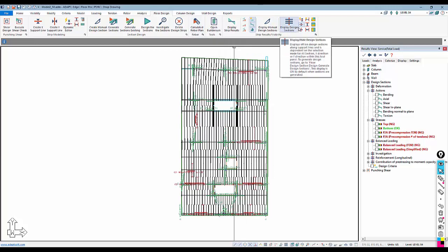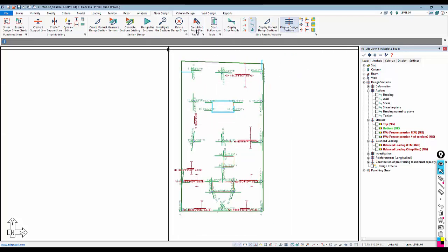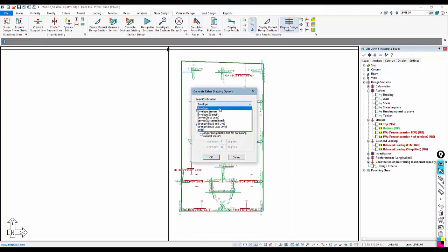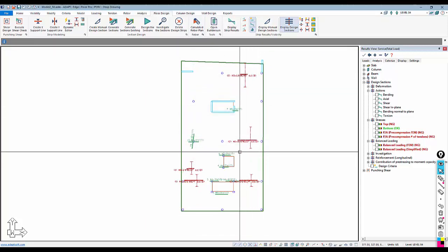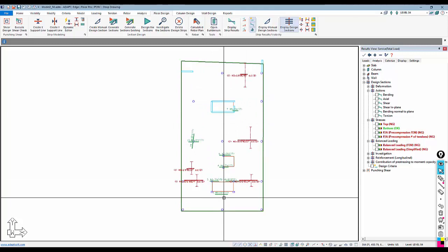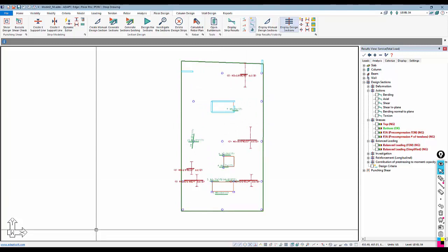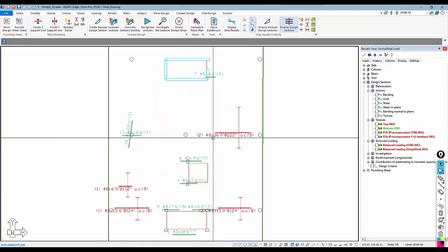If you wanted to determine just reinforcement maybe for strength, I can do envelope of strength. So we have a lot of PT in this slab. We actually only have a few locations where we need reinforcement to supplement the post-tensioning to meet the demand. For example, here we need 2 number 8 bars in addition to the post-tensioning.